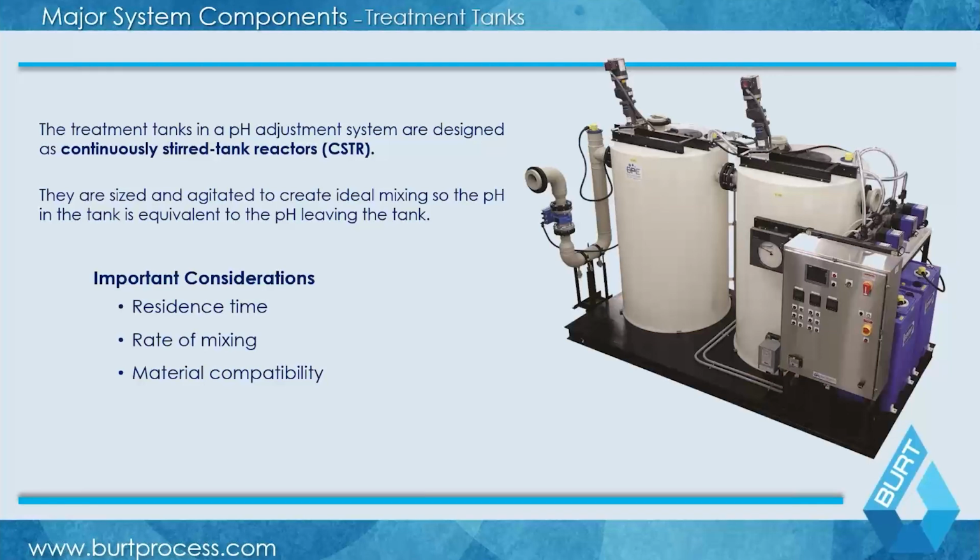Most treatment tanks are going to be some kind of a thermoplastic material, but they're going to be polypropylene, rarely polyethylene in very small situations. Fiberglass potentially for very large applications. If you're doing a system which can be rated to a much higher flow rate, you may end up with a fiberglass tank design, as well as stainless steel potentially, although again polypropylene is by far and away the most common, which you see here in this case.